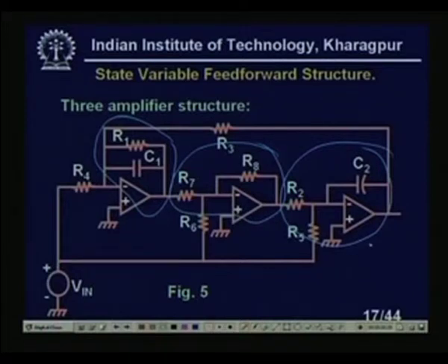another integrator. And we see here there are feed forward paths through R6 and R7, because the input is coming here, it is going through R4 to the first amplifier, then through R6 and through R5 we are giving 2 feed forward. This type of structure can generate any filter functions. Okay, we will see that's the advantage of this type of structure, a tremendous advantage. It is available in cheap form also. National Semiconductor makes these filters, called universal filters, where you can have 1 or 2 elements outside which you can tune to get your desired value of omega p and Qp, right.